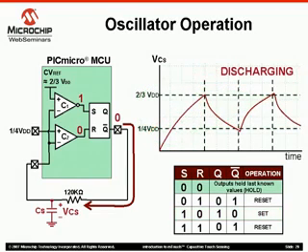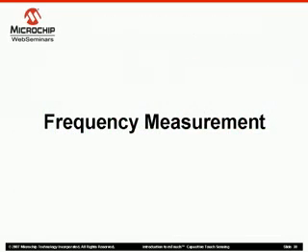We have implemented the RC circuit containing the sensor capacitor into a very good relaxation oscillator. As the capacitance changes in the circuit, so will the RC time constant, changing the frequency of oscillation. So let's look at how we will determine a sensor touch based off of this frequency change using a frequency measurement circuit.